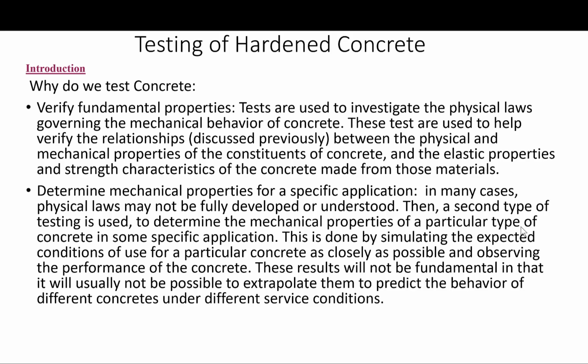So, why do we test concrete? There are a number of reasons for carrying out tests on hardened concrete. On a fundamental level, tests can be used to investigate the physical laws governing the mechanical behavior of concrete. Such tests would be used to help deduce and verify the relationships described in the previous module between the physical and mechanical properties of the constituents of the concrete and the elastic properties and strength characteristics of the concrete made from those materials.